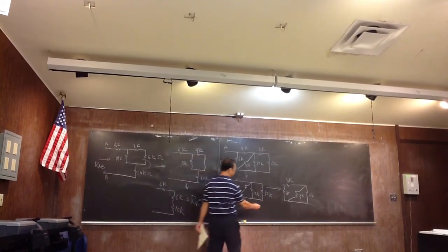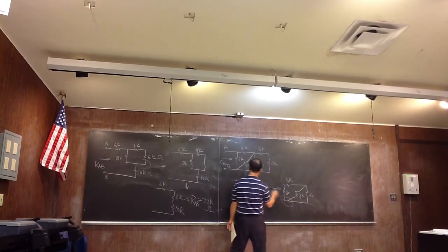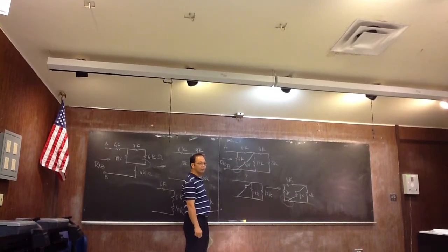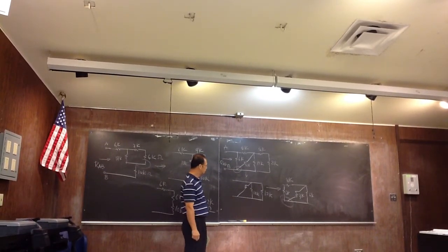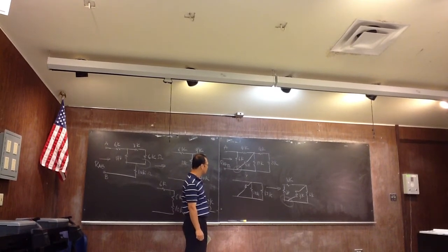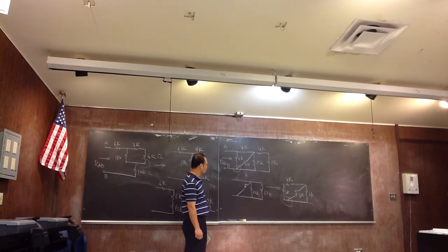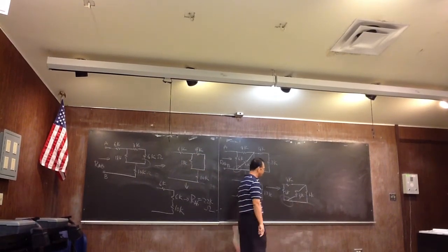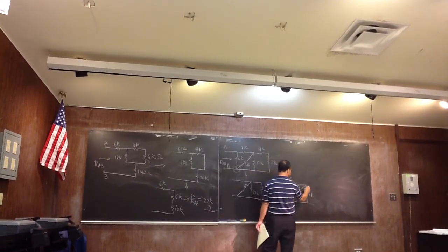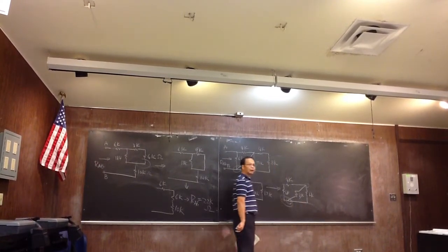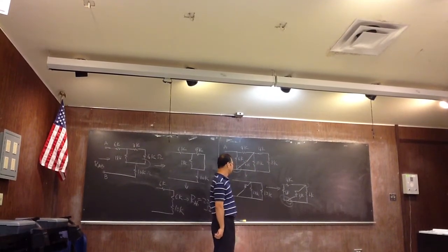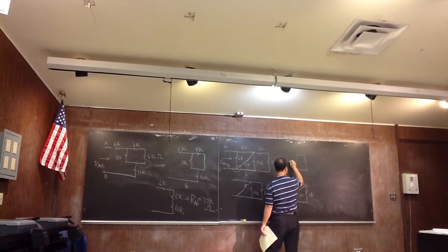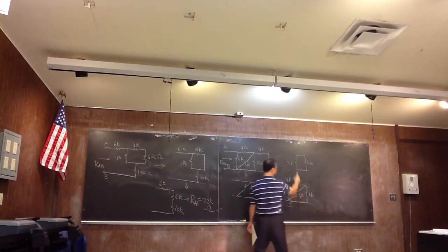Now you see, the way I drew it like this is the same as that. Got it? It's all just a piece of wire, the same connected node. Right? Now, are these two in parallel? Right, because they have two common connecting nodes. Of course, that's the same as that. It's the same, huh?